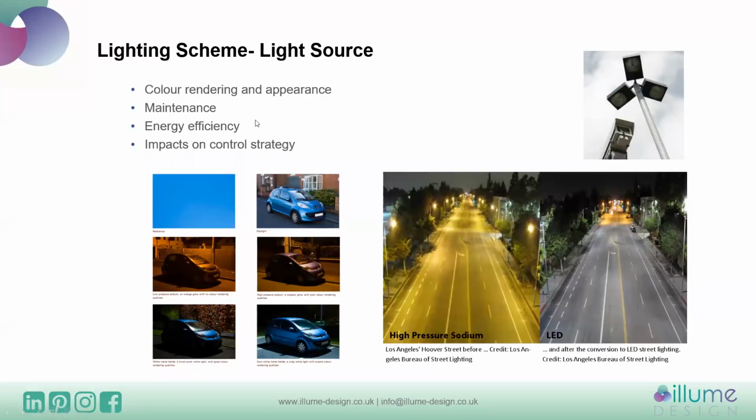The light source choice also affects maintenance, energy efficiency, and has impacts on the control strategy that you can use. With LED now, we can have control strategies that are able to dim and switch off instantaneously. So it's a benefit over discharge lamps, like sodium, where we couldn't do this because they have a different restrike time of maybe even 10 minutes. So they can't be switched on and off easily.